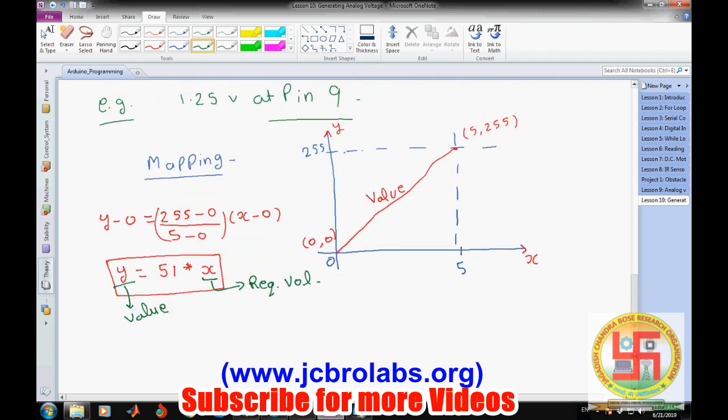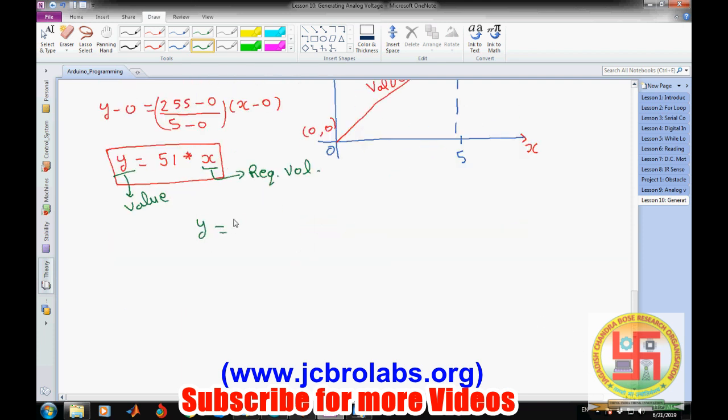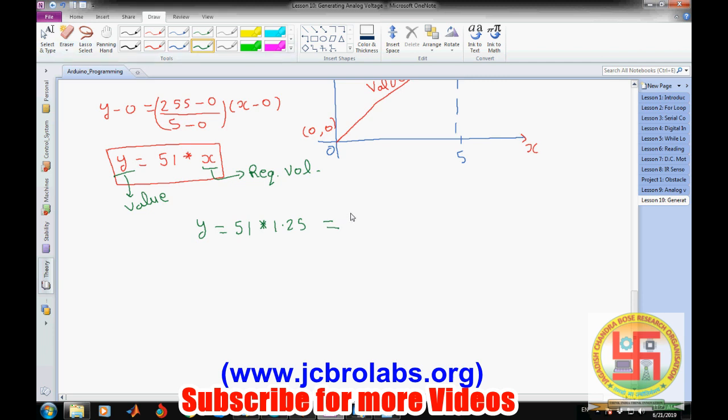As we talked about, we want to generate this 1.25 volt, so y should be equal to 51 into 1.25. Let's do some calculation: 51 into 1.25. So it is 63.75. But as I said, we can only send the integer value, so it will be approximated to 63 only.